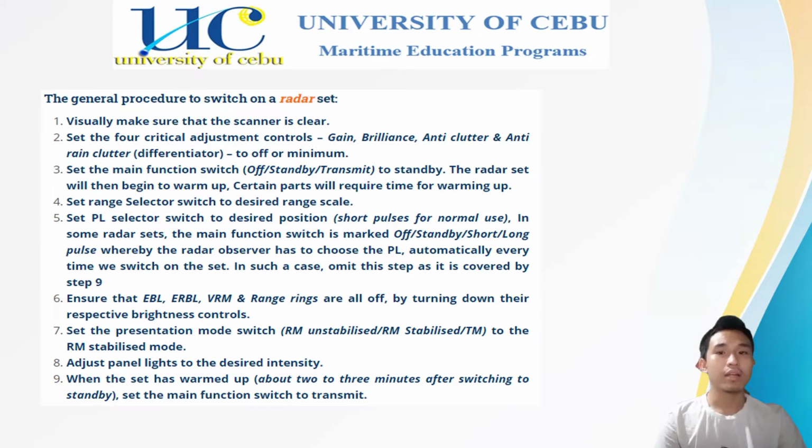Eighth is adjust panel lights to the desired intensity. Ninth, lastly, when the set has warmed up about two to three minutes after switching to standby, set the main function switch to transmit.